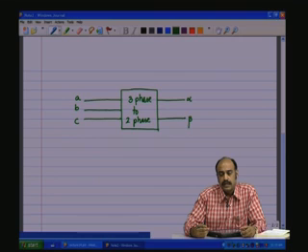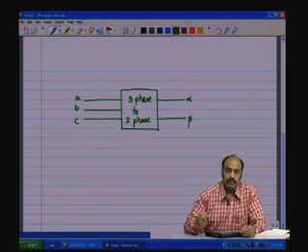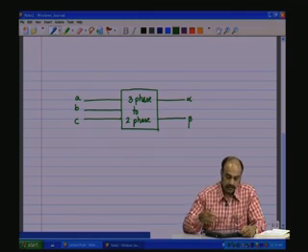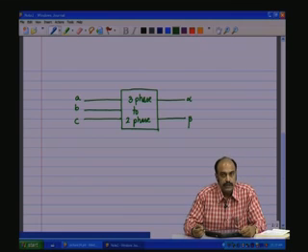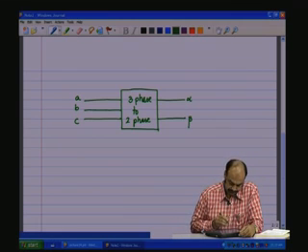probably would be in sensing a 3 phase signal like a current or the voltage, and then converting it to 2 phase coordinates, which will give a resultant, especially in applications like vector control or 3 phase control and those kind of applications, where you need to convert from a 3 phase to 2 phase system, and this could be a sensing transformer which could do that job. Anyway, there are a few applications for these.